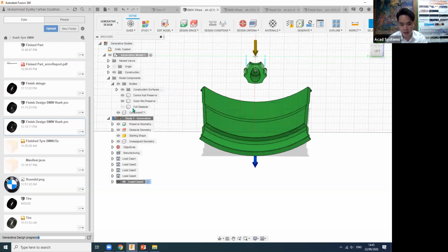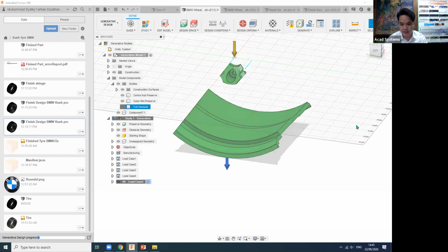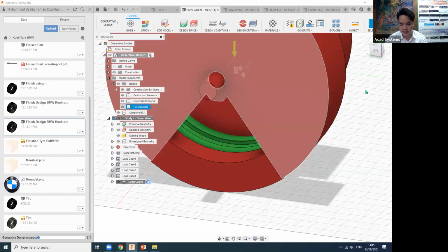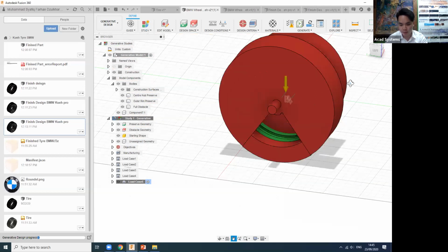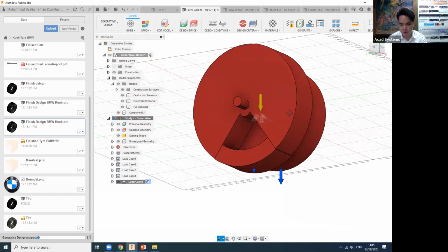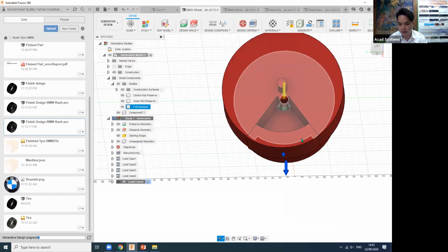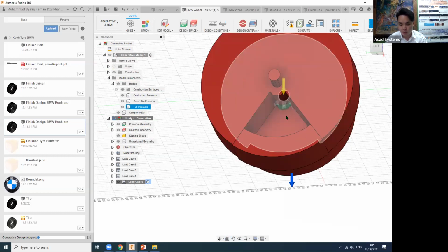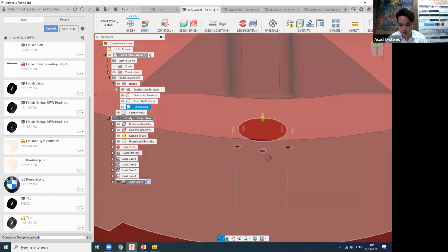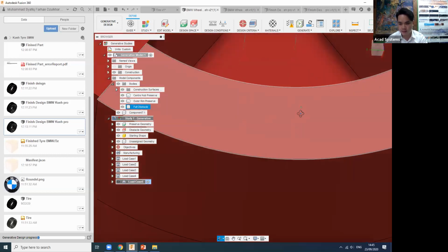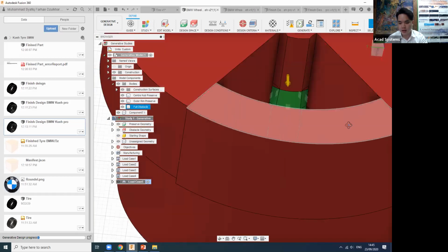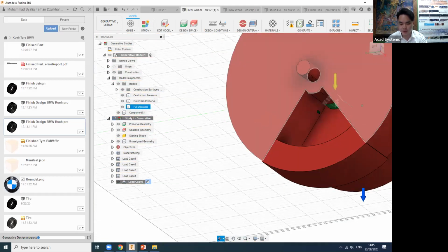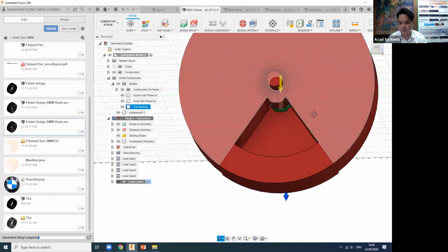You can create a full obstacle. I can create the isolation, and you can see all of these red things. This is just for blocking. What are they blocking? They block the generation into other spaces that I don't want. So you can see here, there's only this part to this part. These two are the space for the generative design to generate by itself.